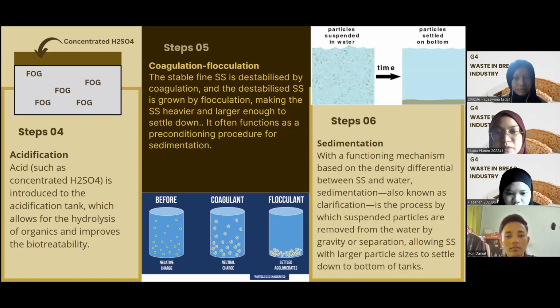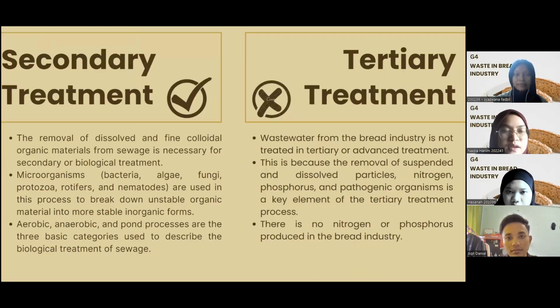And the last one is sedimentation, which is a mechanism based on density differentials between soluble solids and water. Sedimentation, also known as clarification, is the process by which suspended particles are removed from the water by gravitational separation, allowing solids with larger particle size to settle to the bottom of the tanks. Next slide. So the last one is secondary treatment.